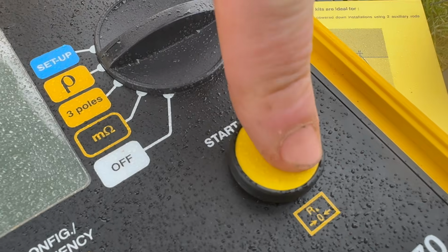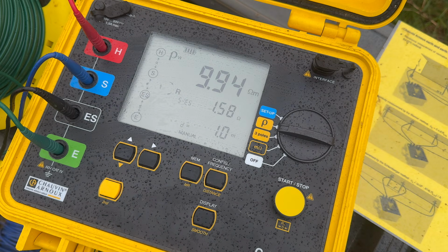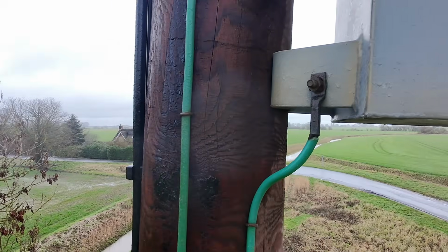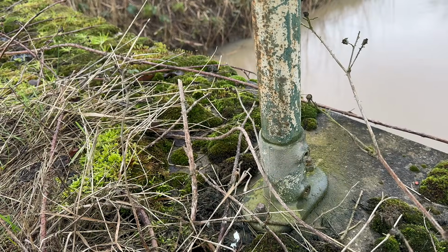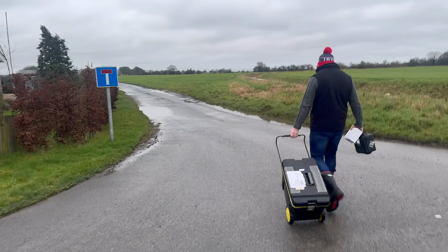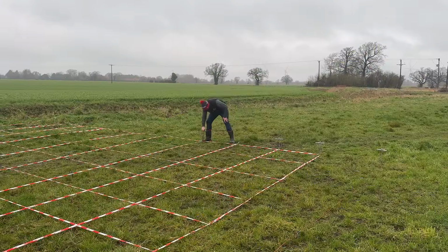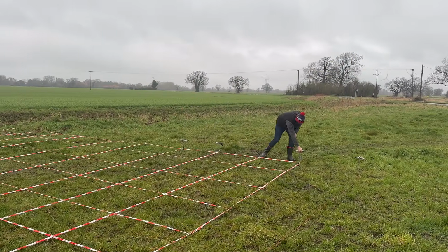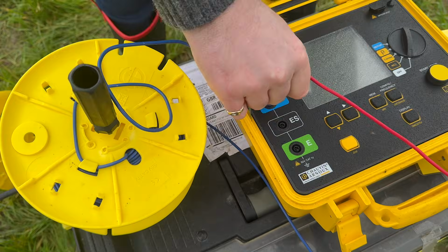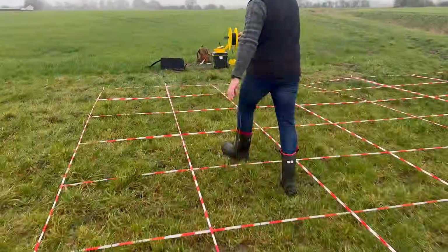The result is a resistance reading that looks very good on the tester, but that figure is no longer representative of the soil. Instead, you are measuring a combined network of soil and metalwork, which masks the true resistivity of the ground. So is there anything we can do about it? Well, you're not going to be able to rip out metal fencing or a pylon, but we can do a resistivity test. By spacing the probes correctly and separating current injection from voltage measurement, the influence of most parallel paths is reduced, allowing the test to focus on the soil rather than the installation.